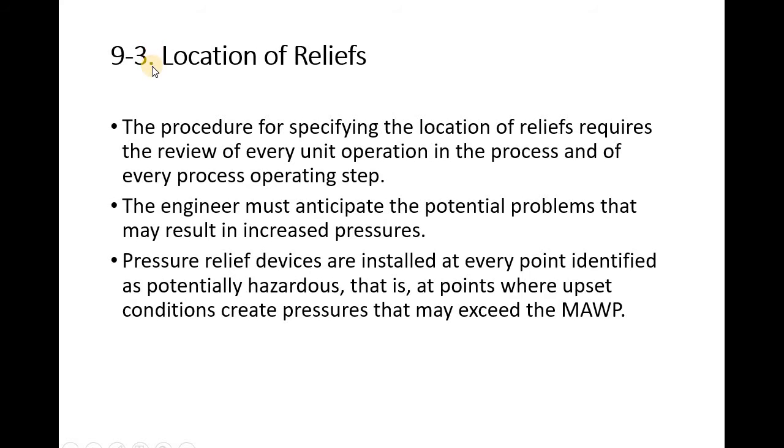Okay. Now we need to look at where we should have our relief valves. Do you think we should have it at the input or the output or the top? The answer is always at the top. Okay, the answer is always at the top. So if you just read the procedure for specifying the location of reliefs, it requires a lot of information, the review of every unit operation, the process, and every operating step. So it's not straightforward. I've just told you a generic thing.